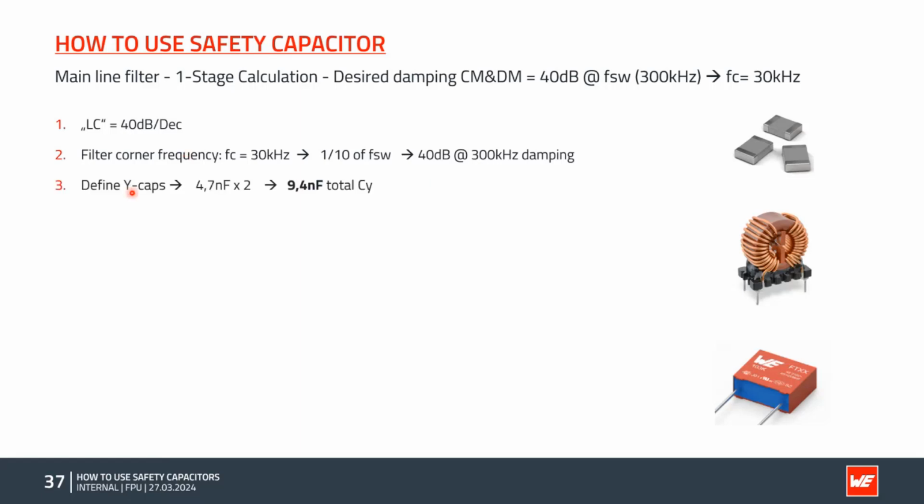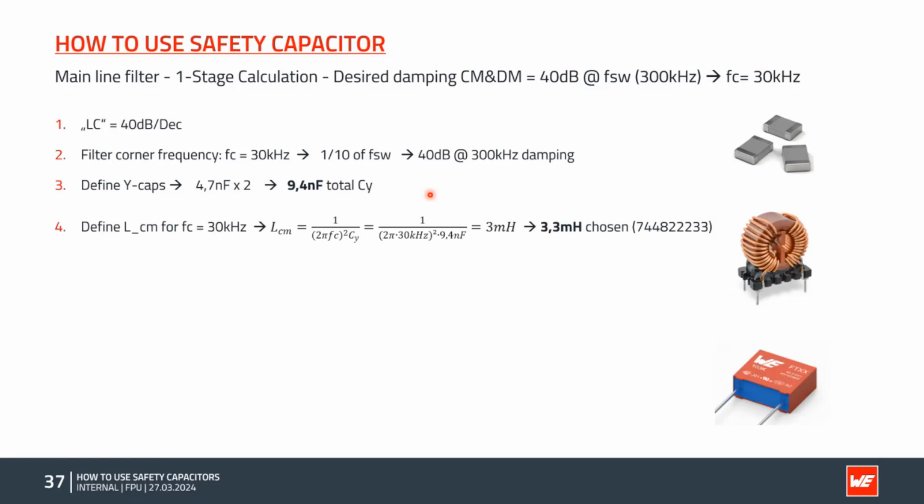Then we define the Y caps. In this example, we do it from a rule of thumb, and say 4.7 is a good value. So we have a total of 9.4 as a Y capacitor.